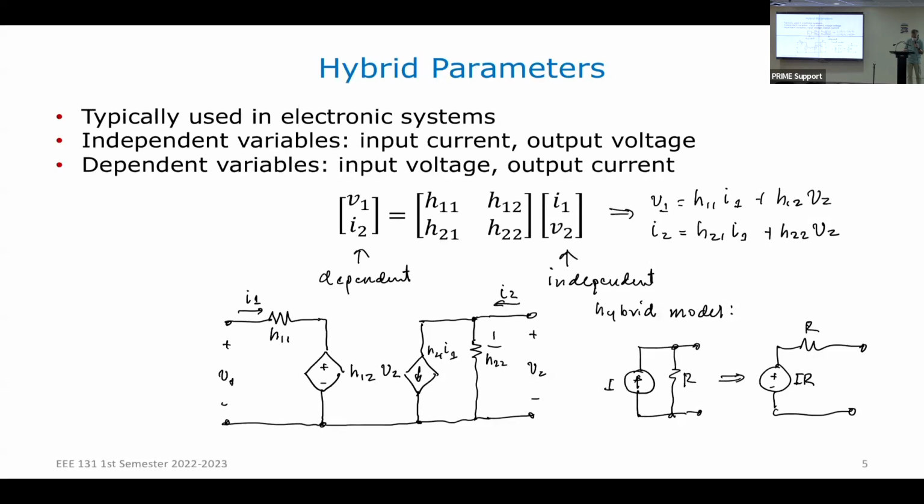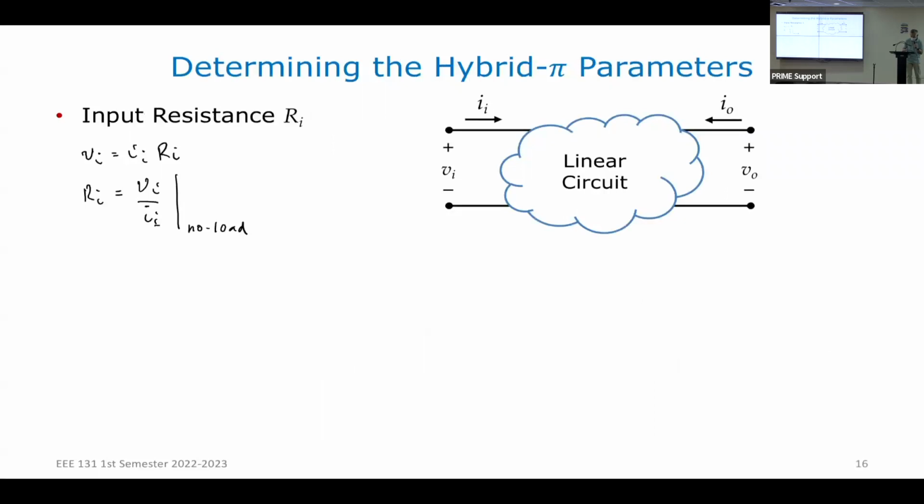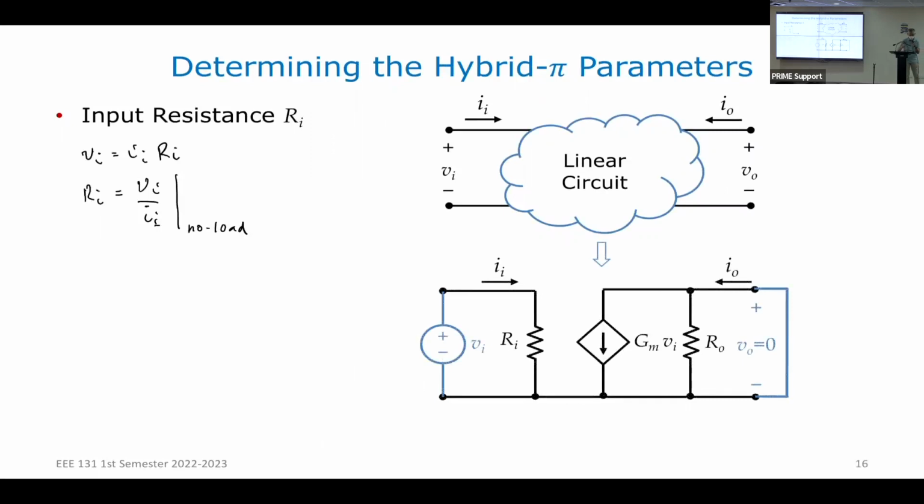So, like I said, even if it looks like it doesn't matter, as a matter of practice, whenever we get the input resistance, we short the output. Short the output if it is the Norton model, open the output if it is the Thevenin model. Okay. Any question with regard to that? That is the only thing that you have to remember, the no load condition.